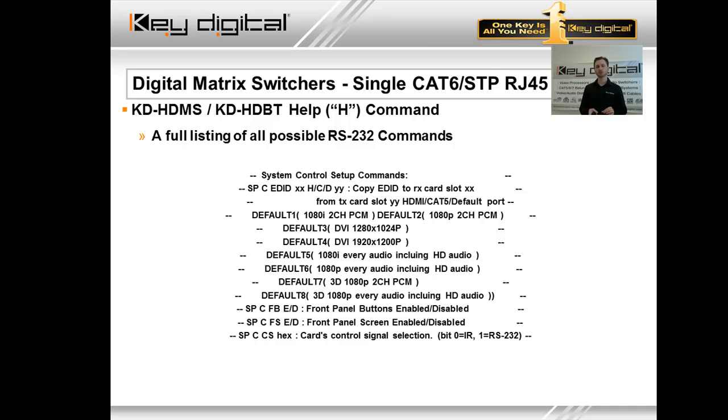But you have to tell each card, hey, am I an IR card or an RS-232 card, before you do the routing, because it's handling a certain type of signal. So that's a part of what we're doing. And where you see hex there, we're going to discuss that in more detail, but we do use some hex values determining what's IR and what's RS-232.